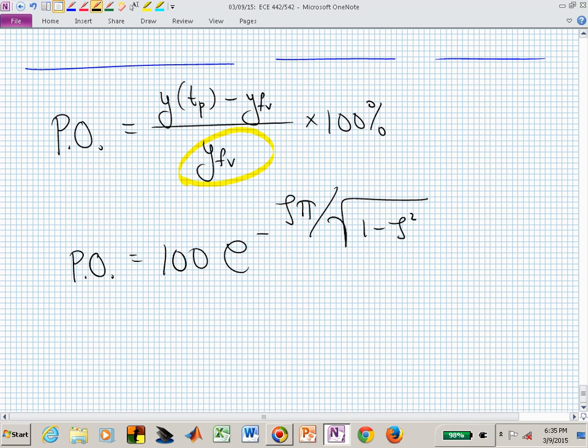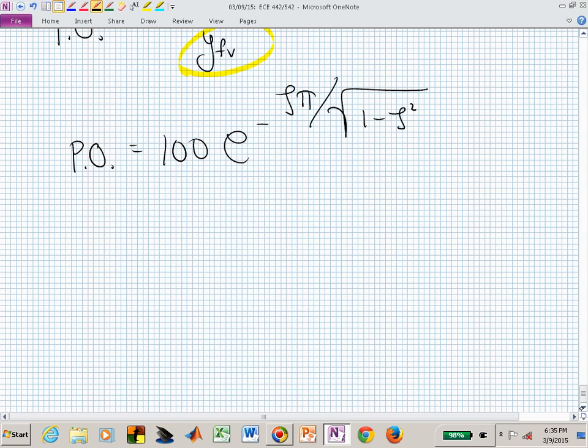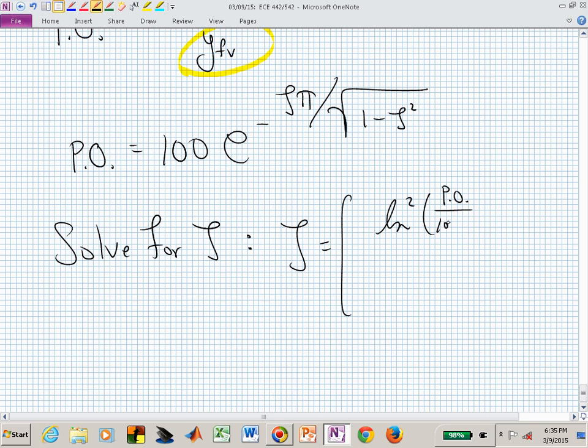And this now allows you to solve for the damping ratio, which says if somebody gives you a particular percent overshoot, you can tell them what your damping ratio needs to be to accomplish that percent overshoot. And you can derive this. You might want to do this on Pi Day. Since this won't be on exam number 2, you don't have to do it before Wednesday necessarily to derive this, but there's pi squared in the denominator, and what's that roughly?